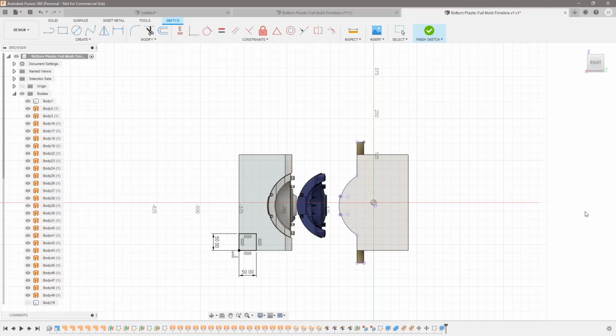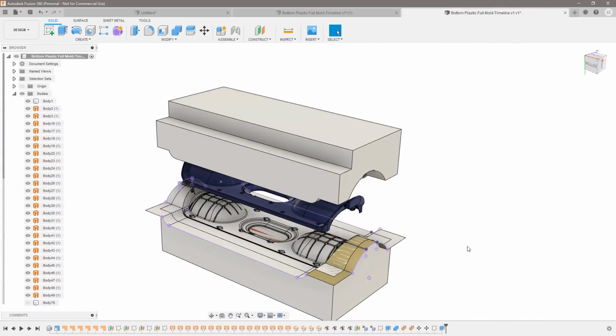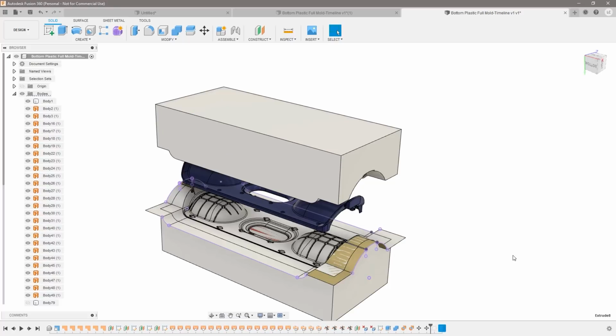You should be aware that in the background of a solid modeling tool, the software itself is just keeping track of points, edges, and faces, and they're all assigned IDs. If any of those breaks, that's when you can run into problems. So if we put in our square, we extrude it all the way down the edge. But if I draw this one back, and I, for example, decide to open another sketch here, this is going to happen.